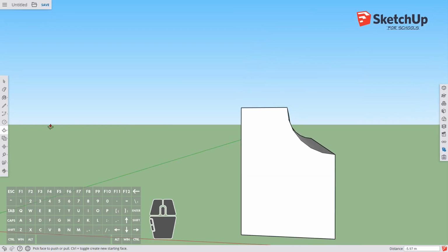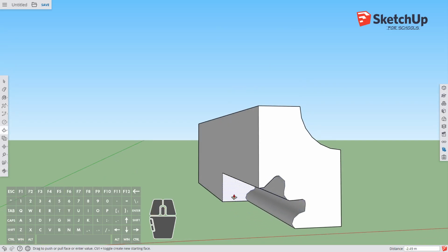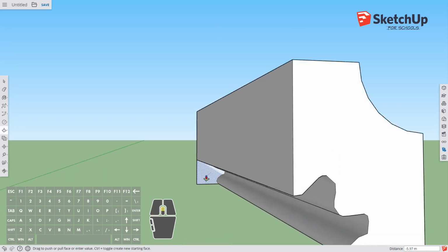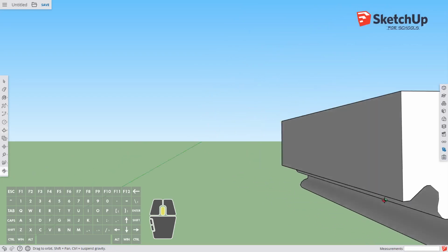Now, it doesn't have to just be a circle. You could, if you wanted to, draw your own shape and maybe your own curve. So if I draw just a freehand line to the edge, exactly the same thing will apply. So if I click on my push-pull tool, again, that's created a new face on that shape. I can click, go all the way back, and then when we get to the very edge, you'll see that mirrored effect started again. It says on face, I can click, and it will now cut that shape out of that shape.